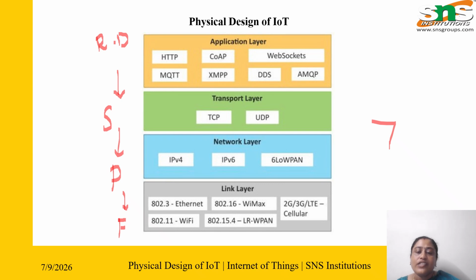Based upon the medium, different protocols are used. If the range of the networking device is short, we can use the Bluetooth protocol or Wi-Fi. If it is less than 5 kilometers, then we can go for 2G, 3G cellular protocols. If it is less than 100 kilometers, we can go for LoRaWAN. You can use Sigfox. All these protocols are responsible for effective communication and seamless user experience.